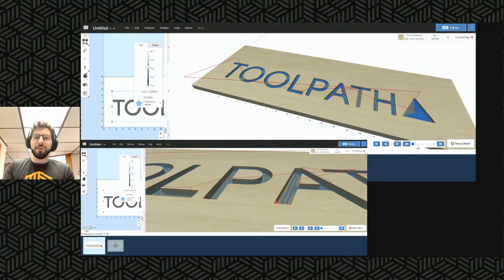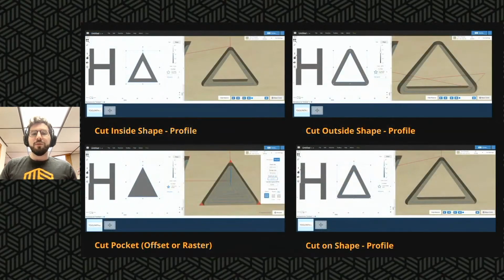Great. Thanks, Neil. So first we want to know what toolpaths are in Easel. The general idea is a toolpath is a path through space, the X, Y, Z coordinate plane in your machine, that the tip of a cutting tool, like your V-bit or your end mill, follows on its way to producing the desired geometry of the workpiece. So in Easel, you take the design, and Easel applies these toolpaths to your design to create a finished part. In Easel, there are 4 basic types of toolpaths.